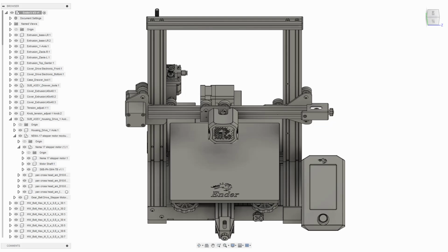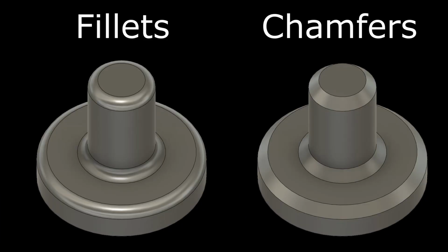First, unlike in CAD programs, your ability to organize components in a hierarchical fashion is rather limited, and there really isn't any support for joints. Some tasks require a lot of creativity, since you're often pushing PrusaSlicer well past its intended modeling capabilities. Things like fillets and chamfers are possible, but are potentially messy and clunky, especially for non-straight edges. Since PrusaSlicer doesn't support design constraints, parametric modeling, especially with multiple subcomponents, can often be tricky.